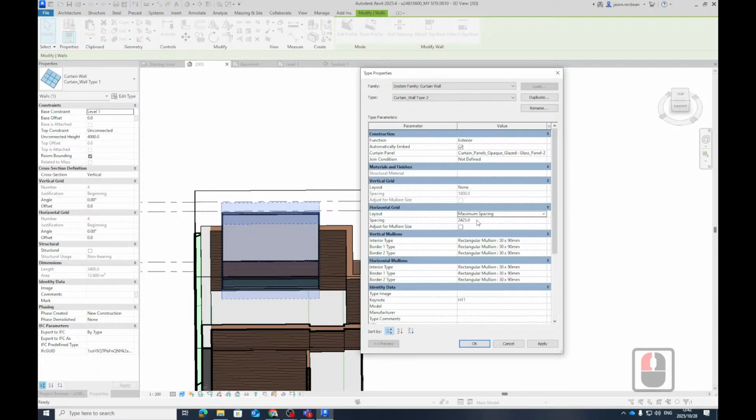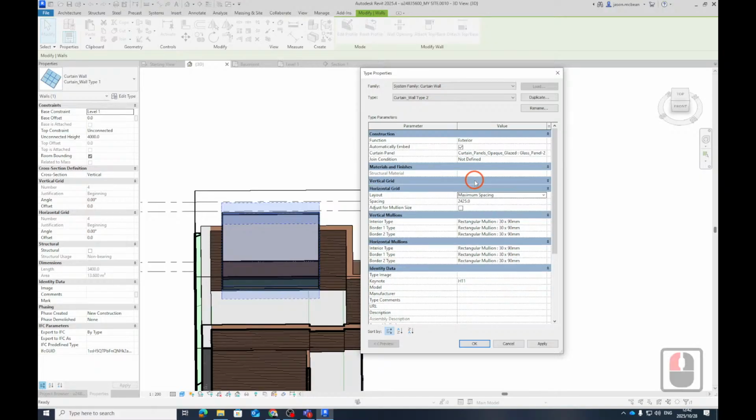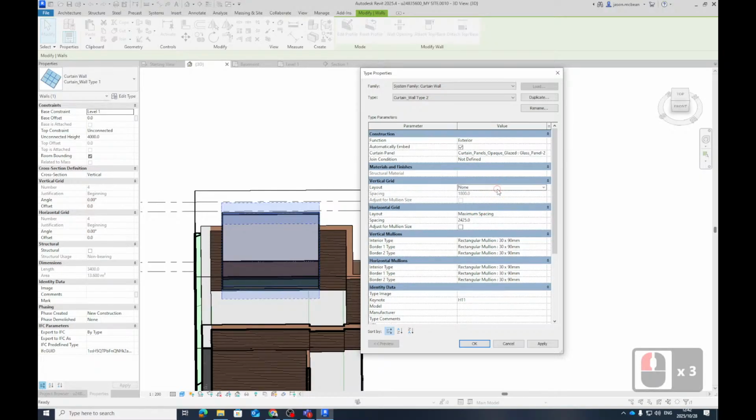The highest they can make it, because the glass panels that you can buy, it's got to do with the glass panels. The glass panels are the limiting factor, because of their strength, you can only buy them in certain sizes and strength. And they're laminated glasses. Those are laminated, so if you try and run through it, it will shatter and fall on the ground in a big heap and won't break into shards and cut you. It's very deliberate. Now those things you can only buy in certain sizes. So now vertically, I know for a fact maximum spacing of 1800.